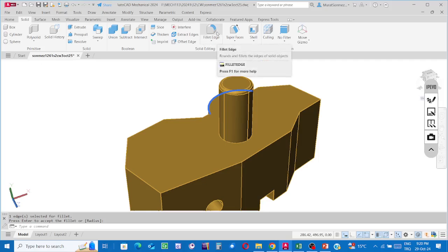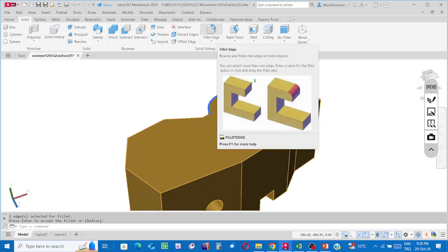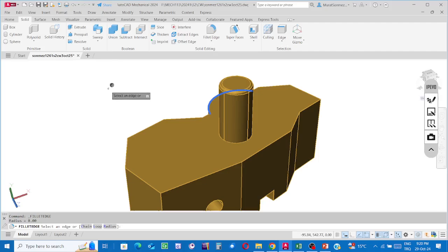How about filleting? Use the same facility. For the rounding radius, select the down direction key of the keyboard. If you have a tiny arrow within the compartment, it implies that there are some options. Clicking on the down direction key of the keyboard can drop the list of the options, and from the list select the radius option, and then the radius in the box, say that it is 8 millimeters.